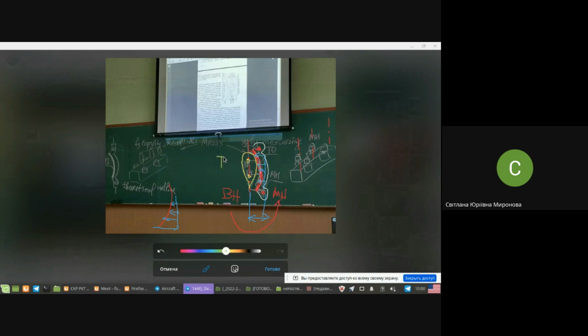It's an old-fashioned way to solve it. Or instead of the template of jig, we might use a CNC milling machine, for instance. Either or, in order to produce these locators. And what we need to produce in the locator accurately, once again, are the red elements. The contour with mounting holes.